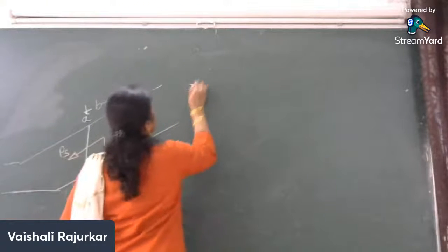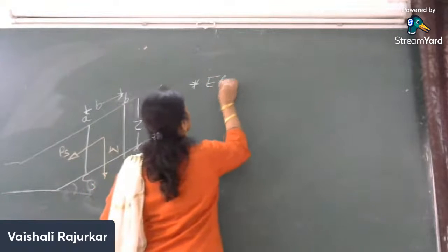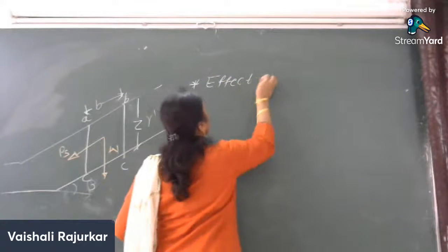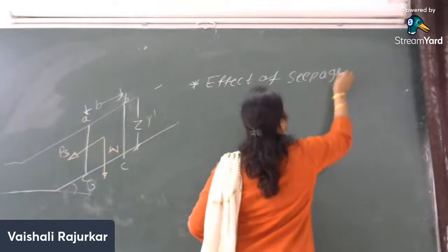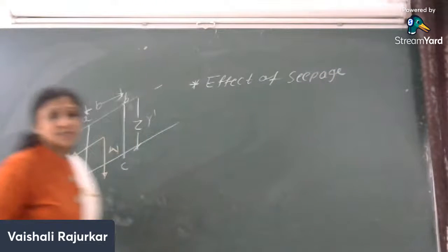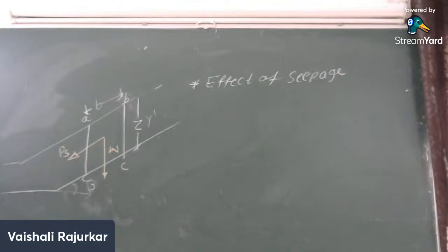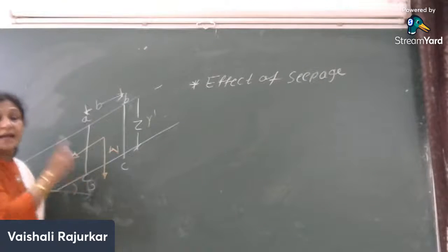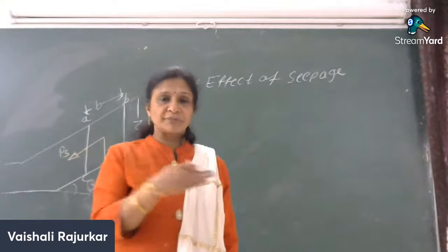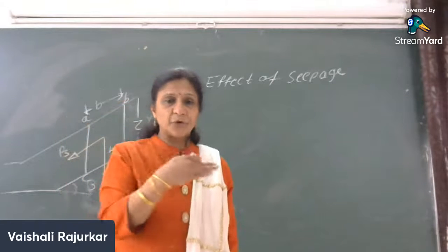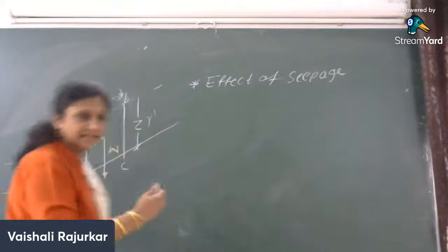Here we will just consider the effect of seepage. Now, what is seepage? Seepage force is denoted by PS, and the seepage force will be acting in the direction of the flow. Where the water will flow, the seepage force is also acting in the same direction.